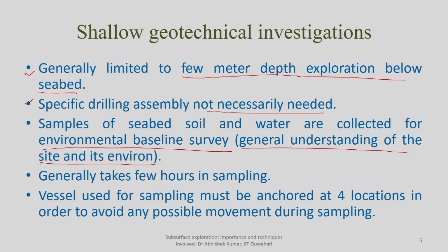Any typical shallow geotechnical investigation, because you just have to collect the sample from the seabed, at a particular site of observation generally takes a few hours, maybe 2 hours or 4 hours, so that you can collect the soil sample or seabed material sample from your tentative site, then move to the next site.